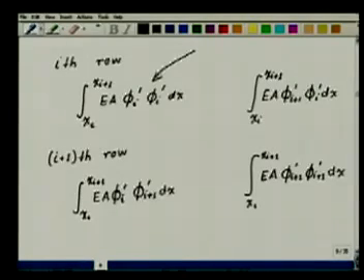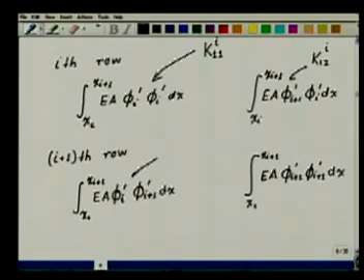to which the element contributes with non-zero entries. So what we are going to do is write these entries in the form of a matrix, and the first entry will be called K11 of element I. The second entry will be called K12 of the element I. The third entry will be called K21 of the element I, and the fourth one will be K22 of the element. Tell me, why am I calling it K11, K12, K21 and K22 of element I?